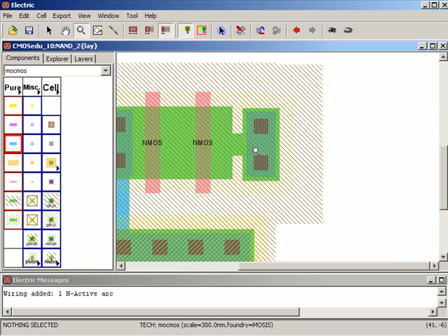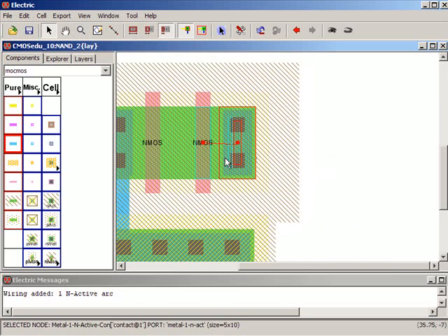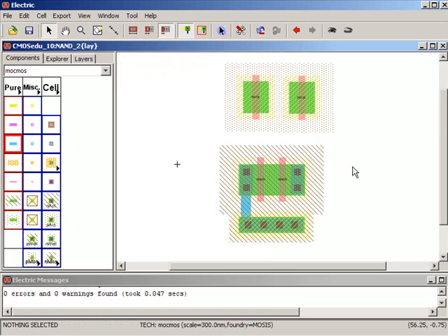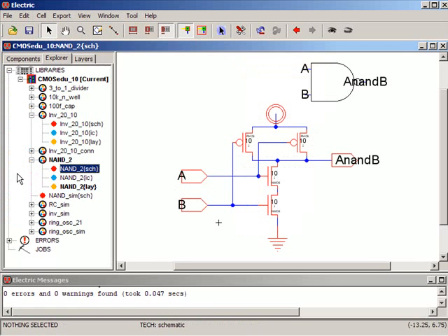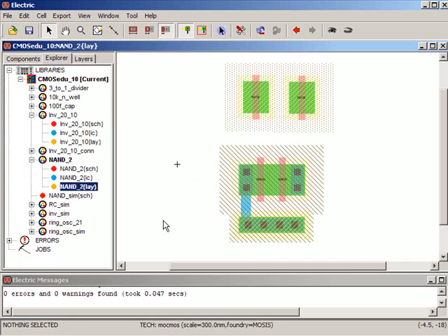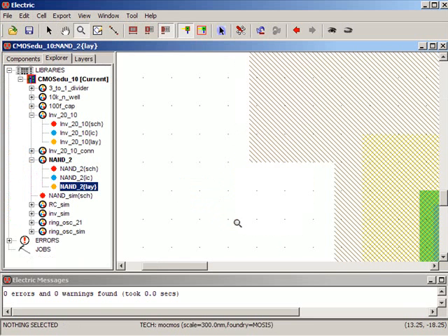I think I'm off a little. I am. Oops. Okay, pull it all the way over. And I think I might be able to pull this one over a little. Let's DRC. Okay, fit. Notice I don't need a connection in here because that's the node in between the two MOSFETs right here. Alright, so let's do a DRC one more time. No errors. So let's just zoom in on this. Do a Control G. Look at the grid.